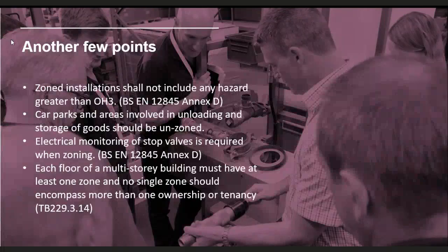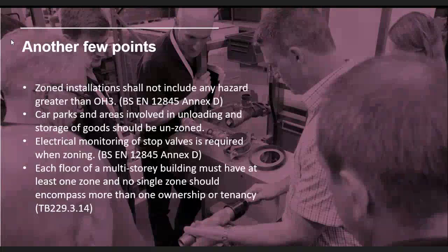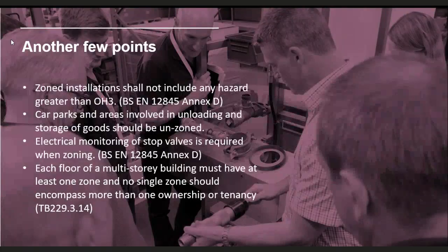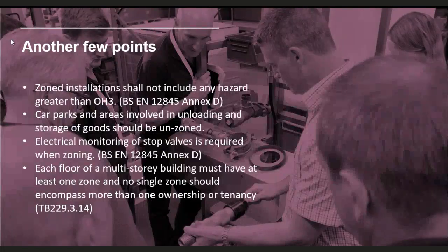The reason being, I think, is the signalling, but also just the hassle and disruption, really. Shop units change hands quite often, so one owner is going to move out, a new owner is going to come in. They want to do some changes. They want to refit the shop. Often that's going to involve turning the sprinkler system off and draining it down. So if they weren't on a separate zone, then you'd have to say to the shop next door, "Oh, sorry, we're going to turn your sprinklers off because these guys want to do some work."